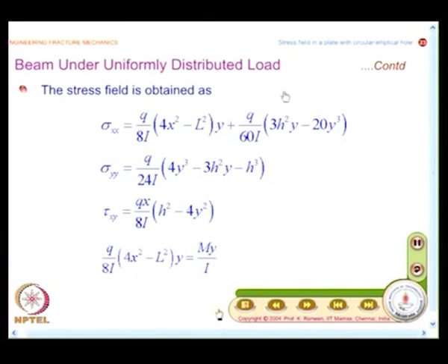Theory of elasticity recognizes the deformation of the planes, because we are satisfying the overall equilibrium condition as well as the boundary conditions and compatibility, and finally we get a solution, because we have not made any assumption on the displacement picture. Displacement is evaluated as part of the solution procedure. So, in a sense, it has expanded the scope of problems that you could solve by the theory of elasticity approach. That is the way you have to look at it.